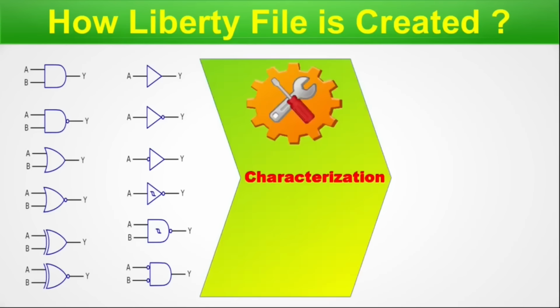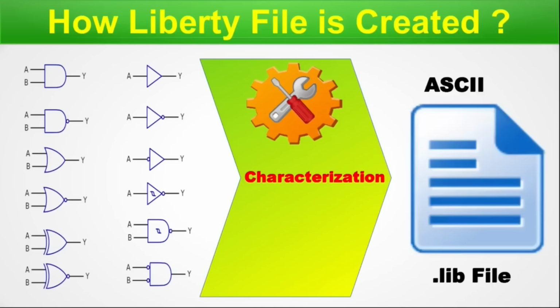In the standard cell characterization, the engine picks up the necessary views for the characterization and runs the dynamic timing analysis, which is already explained in episode 1. In case you have not seen episode 1, I request you to use the chapter facility in the respective video description to quickly navigate and see the relevant section. Now, the characterization process gives birth to the text output file called the .lib file.